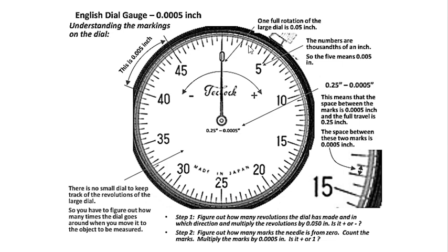You know how many rounds it went for your gauge block stack, and you swap it for the object you want to measure and do the same thing, going in the negative or positive direction, and whether you add or subtract the markings on this side, after swapping the gauge block stack and the object you want to measure.